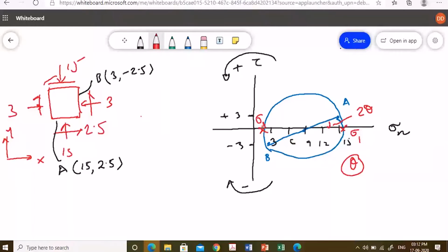So this must have come somewhere around here. So that was basically the plane when I gave you that problem. If the 30 degree rotated, as a result, you are seeing this become negative. The shear stress become negative in that problem. So this is how we basically draw the Mohr circle.